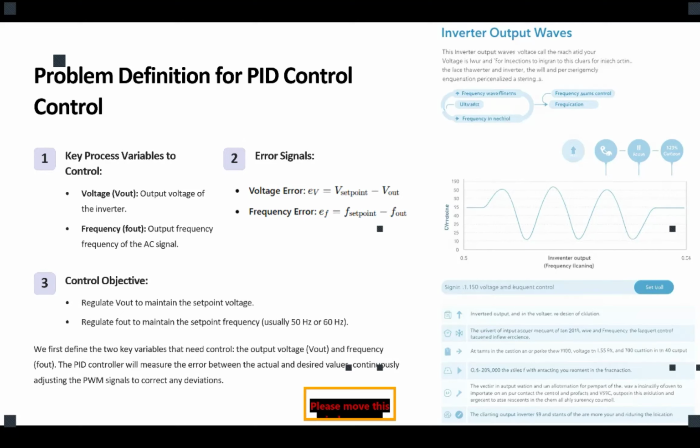In inverters, as we talked about, we have active power control, reactive power control, and frequency control as our primary controls, and current control as a secondary control. We said the current control is basically a protection, it has a protection application rather than actual control. So what actually answers the demand at the terminals is active power and reactive power control.